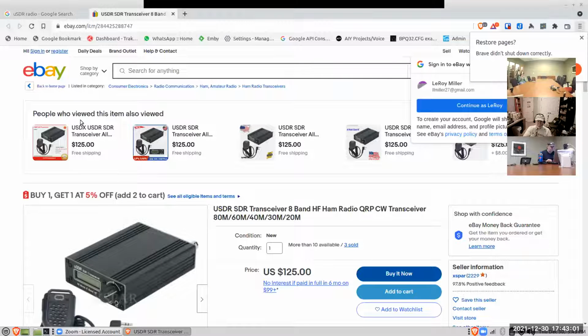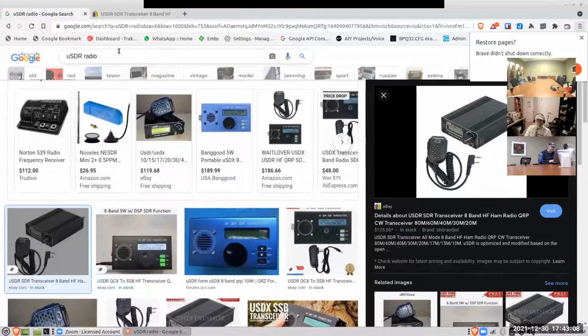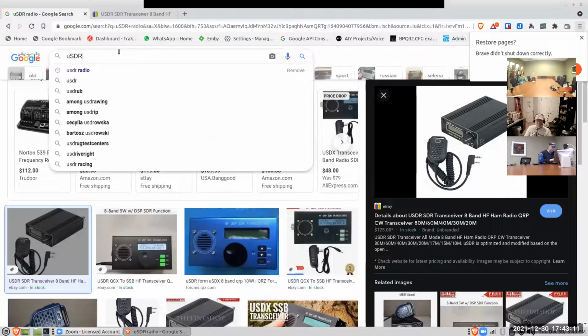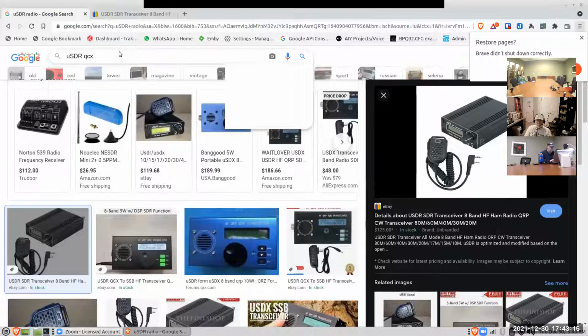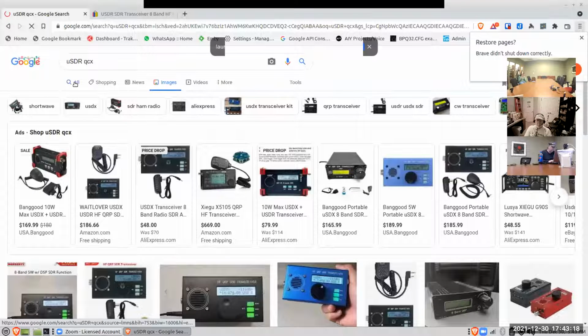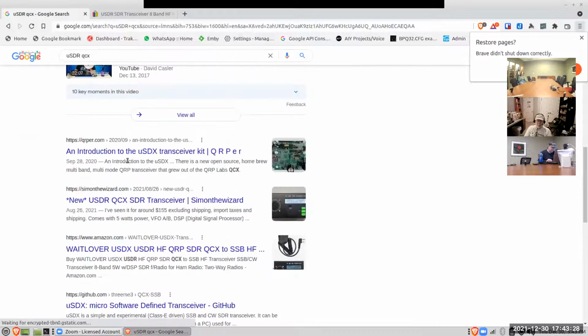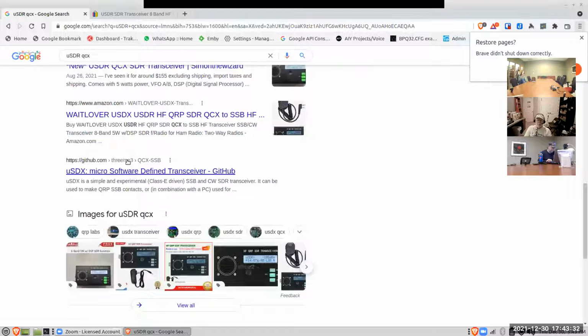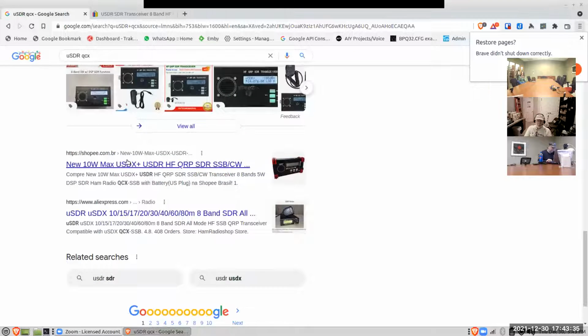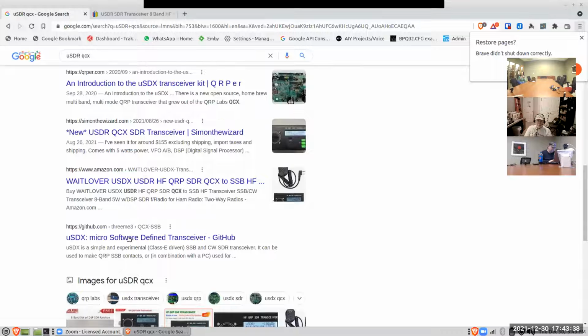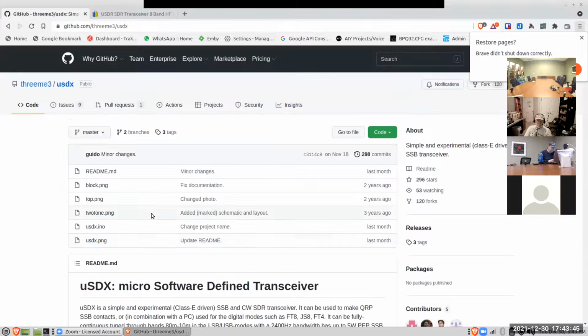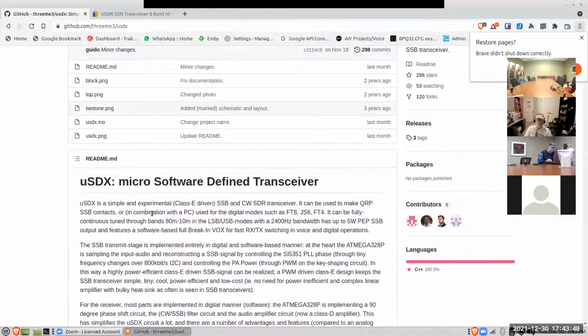Who knows? So I've got the coil wound and mounted on the switch, and now there's another tiny toroid in there to step up the voltage for the LED, and I've got to put that in. It was marked backwards. They said this is backwards, the 2 turns goes on that side, and the 5 turn goes on this side. So I turned it around. Guess what? Mine was correct. So now I had to take it out, and I've got to put it back in. But I'm getting closer. It's a pretty good project. You have to have patience. It's very entertaining if you like to put stuff together. It's not bad. Practice your French a little bit.